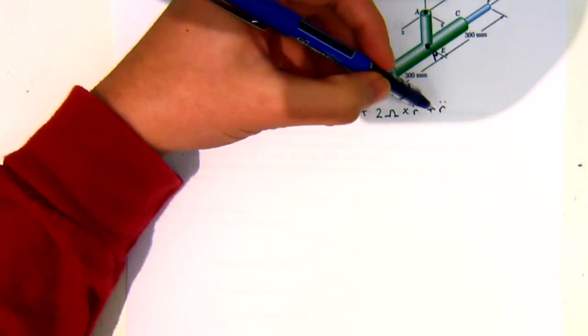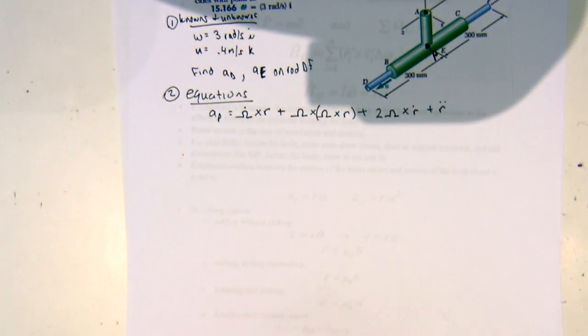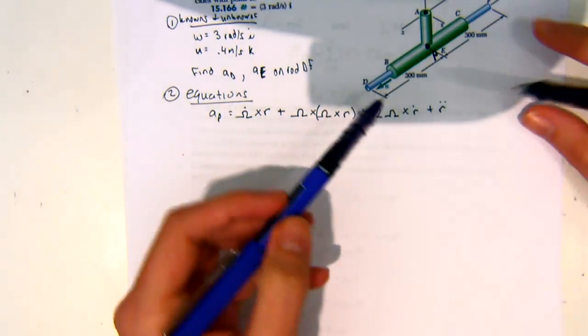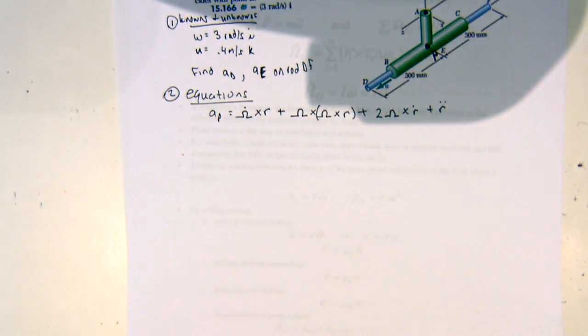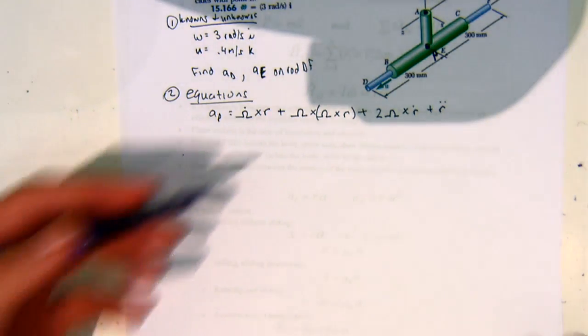So that's the slip. The only time you would have slip is, let's say, if they told you that this rod DF was accelerating, or decelerating at a rate of whatever, that would be slip acceleration. We're told that it moves at a constant rate, so what can we say about slip? Slip acceleration is going to be 0 for both of them.